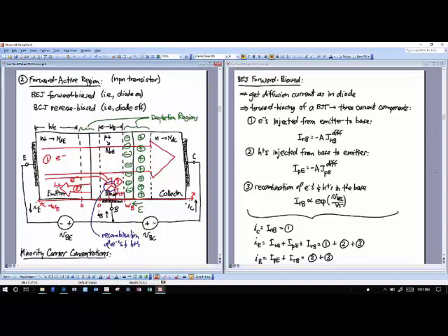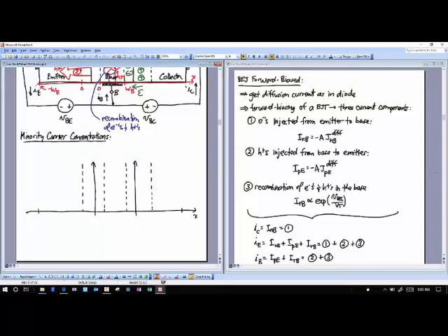Yes? So the current you have going from base to collector, so like that amplified current, isn't that drift current because it's caused by the field just shoving it to the other side? Yeah, I suppose. Yeah, so there's always going to be some drift in there because you've got fields moving currents, but the current originates from the base to emitter junction. And so I'm going to call that drift current, really. And the magnitude of that current is not going to be affected by that field across the base collector. It's going to be affected by the slope of the concentration. And in fact, that's what I'm going to do right now. I guess I'll keep going till our next lecturer walks in, which he usually does.